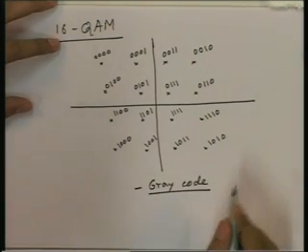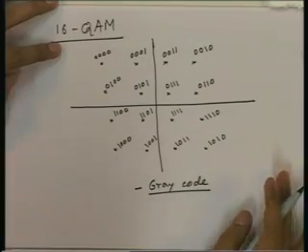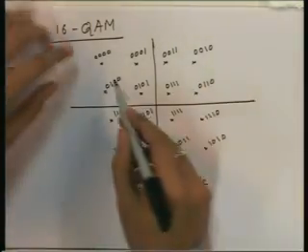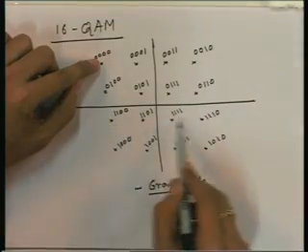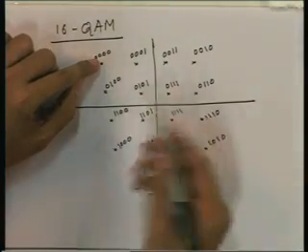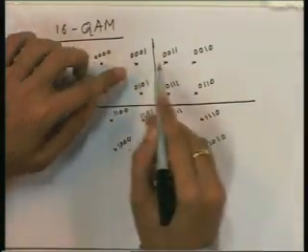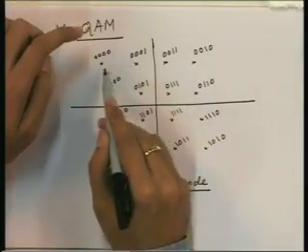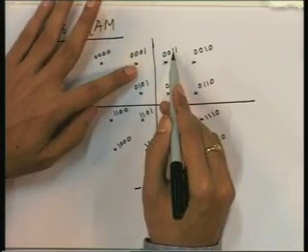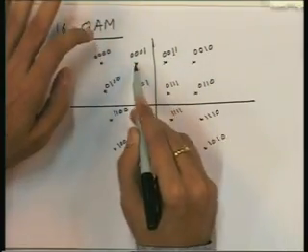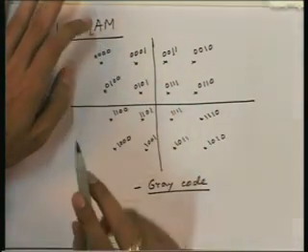for the 16 QAM constellation. Again here you can see that we have not assigned the bit sequences in this order, but we know that horizontally, if we go to neighboring points from here, here or here, there will be 1 bit difference. Here to here this bit is different, second bit is different, here to here first bit is different.